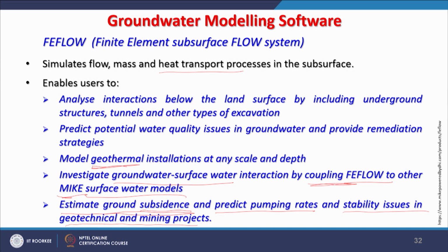Now, the important part here is that whatever estimates we made about the groundwater subsidence can be validated using the SAR interferometry technique, or in short InSAR, by using radar remote sensing. By this we can validate whether the estimates provided by this FE flow model match the real situation with the SAR interferometer, because a few millimeters or a few centimeters of subsidence may not be felt by the people on the ground if no differential subsidence is happening.